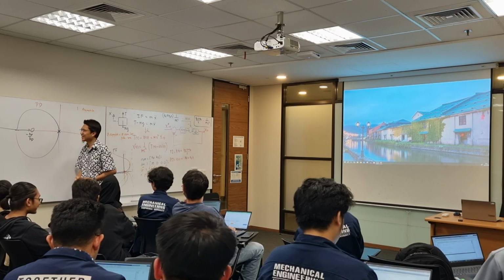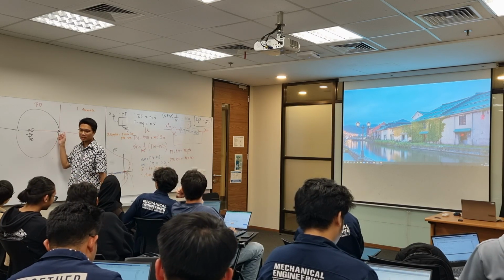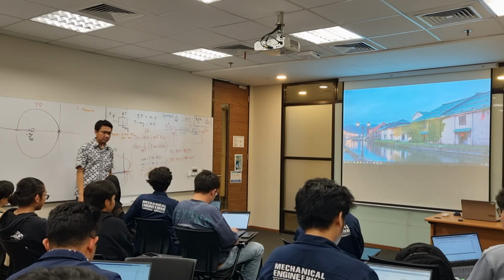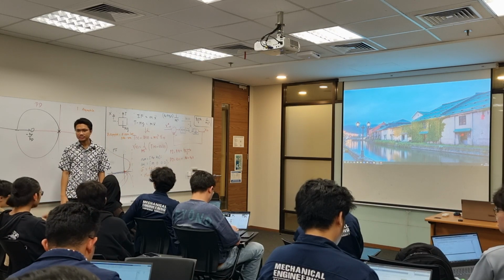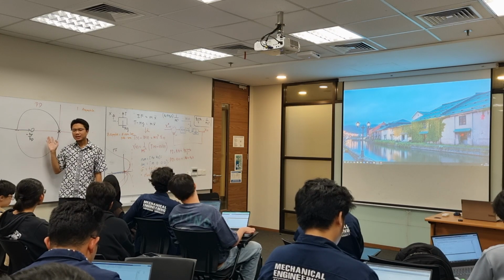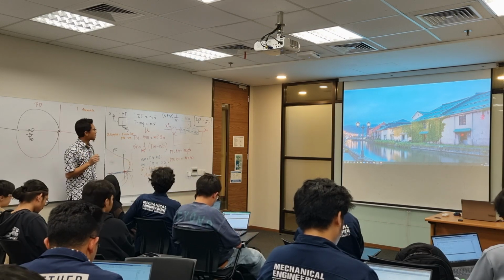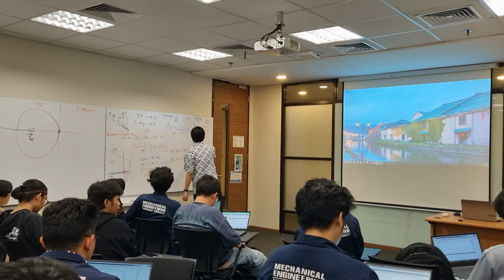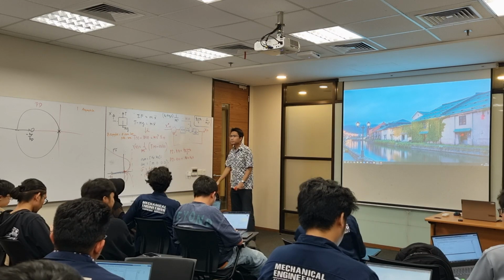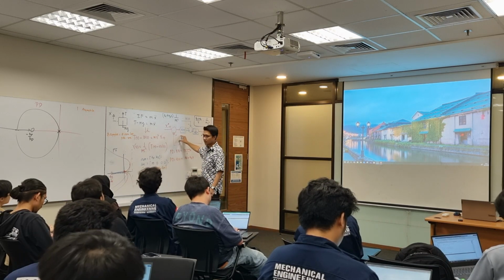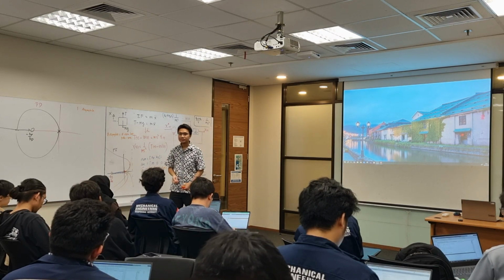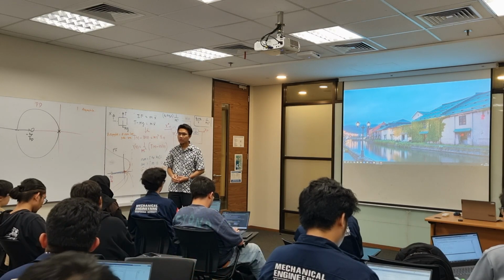Okay. So PD can certainly work in this case, because it has stable closed loop. PID also can. PD will work for the stability, but it cannot track the X star because it has disturbance. So PD also cannot answer the homework. It can only answer the stability problem. For homework, the correct answer is PID.